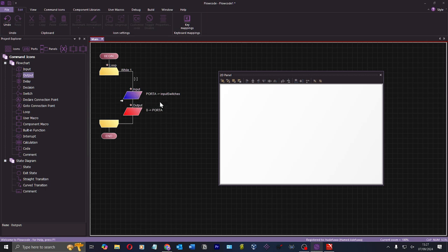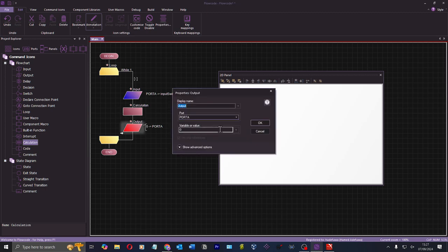So read or write my. I'm going to read my inputs into input switches, and then I guess I'm gonna do something with it, aren't I? I'm gonna do some sort of calculation with it, and then I'm gonna write that calculation output. So let's put a variable called output LEDs.